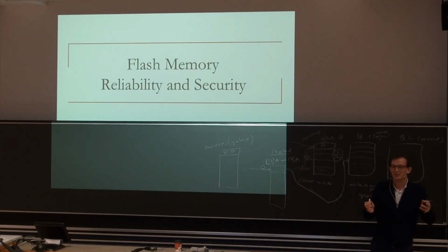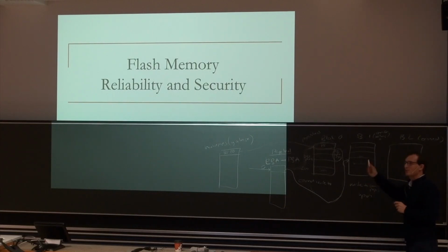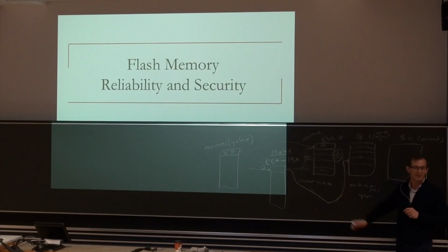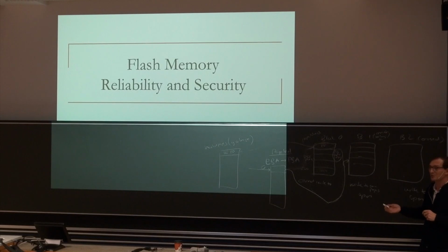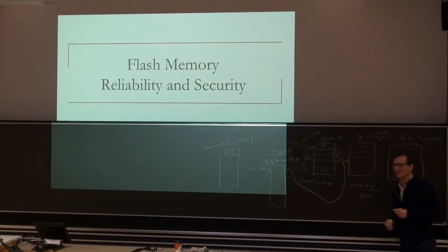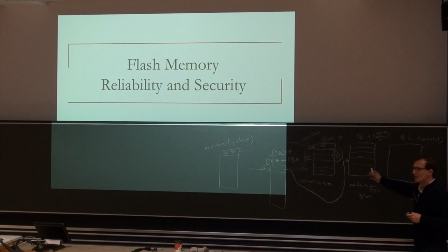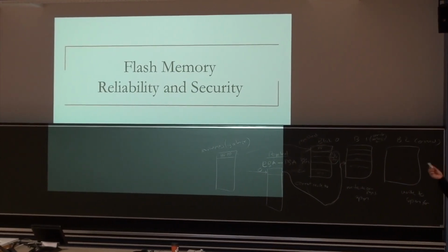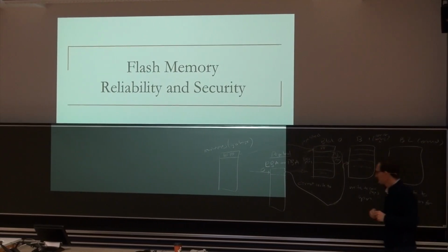And also there are other issues. Like if you say, okay, I'm going to collocate these blocks that are read very heavily in the same block, there are other error mechanisms that you need to watch out for, because there are read disturb mechanisms that we're going to talk about. If you're reading a particular page a lot, you're disturbing other pages. So your reliability for that block may go down, and you may need to have more ECC or other mechanisms for that. So what data to place where becomes very, very interesting, given all of these different constraints. And there are many different constraints, and we will see some more of them soon.